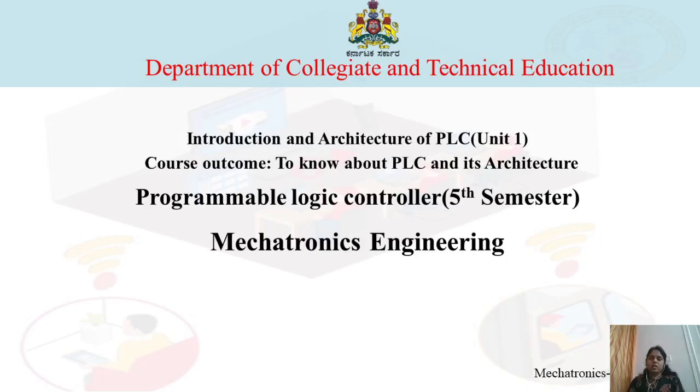See, in the relay logic control, you will be having so many components and it will be having the elaborated wiring. That is why we shifted to the PLC logic control. Okay. In the PLC logic control, you will not be having so much of wirings. Understood? And next, after seeing the difference between those two, we have seen the advantages and disadvantages of the PLC.